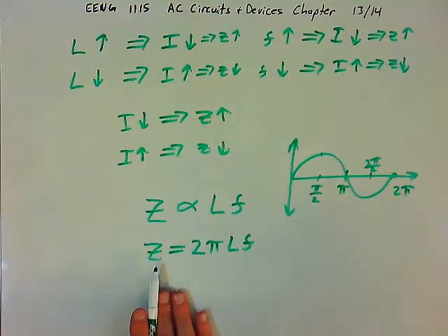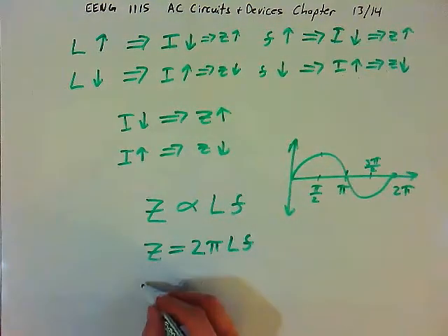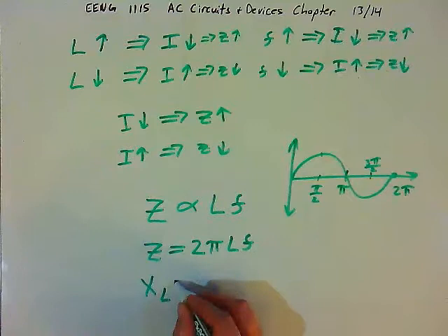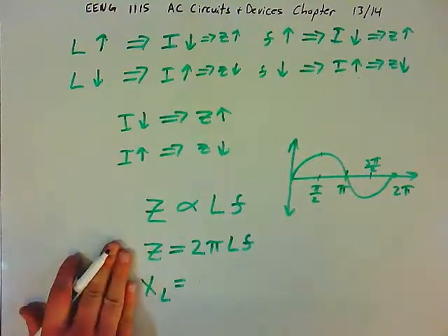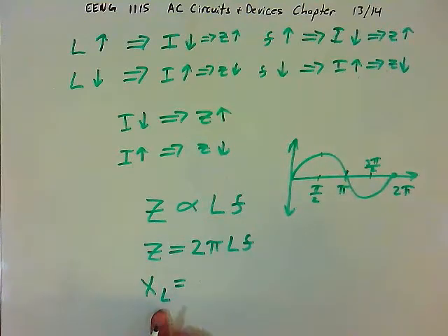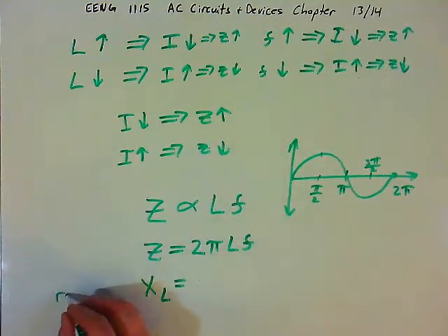And so impedance technically means the combination of resistance and what we call reactance. The inductor itself in the circuit only contributes what we call the reactance. So we've only seen circuits with inductors so far. We've not mixed an inductor and a resistor. And so I've been calling this impedance so far. Technically that's true. But when we go to look at circuits that have resistors and inductors, we want to make sure that we know that the inductor offers what we call reactance.